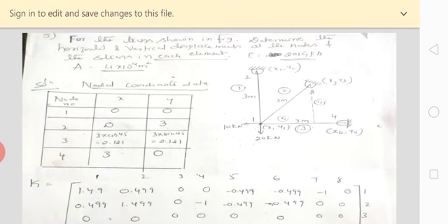Okay, here also this is a 3-bar truss member. For this again, I'm going to read the problem statement here. For the truss as shown in figure, determine the horizontal and vertical components at respective nodes. You are representing Q1, Q2, Q3, Q4, all those are called horizontal and vertical displacement values at the nodes, and stresses in each element. Young's modulus for each element is as given, 201 gigapascal, and area for each element is as given, 4 into 10 to the power minus 4 meter square. Here all the terms are given in terms of meter.